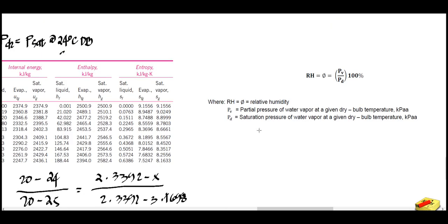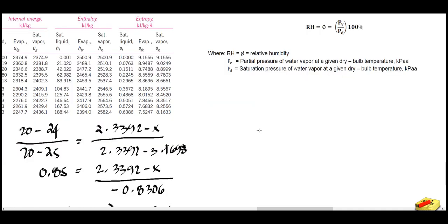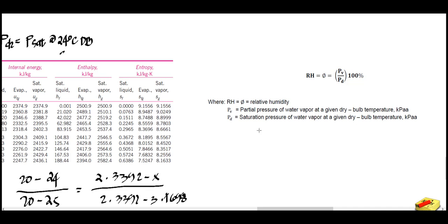So we have now your equation, no, for the relative humidity. So your RH, which is yung RH natin is 50%, no? So from our equation, given the problem, the RH is 50%. So to get the partial pressure, we're just going to derive this one. So that will be your RH multiplied by the PD, so that will be the saturation pressure.